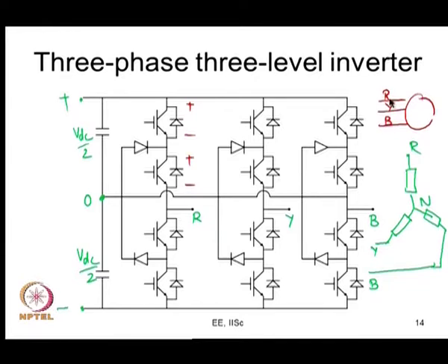Now, let us say it is about 440 volts, you will need a DC bus voltage, the DC bus voltage may be like 700 volts. So, many a times in the Indian conditions for these 400 volt systems, you may need something like 600 volt to 750 volt, not really more than 800 volt, and you handle them using a voltage source inverter with a device, I mean a 2 level inverter's device rating may be 1200 volt. Now, you may have these motors which are rated a few kilovolts.